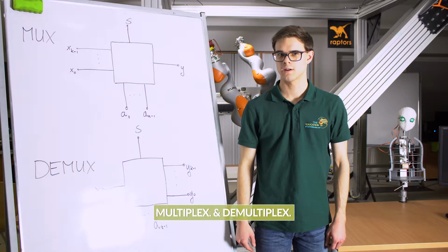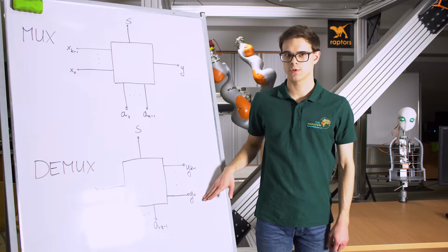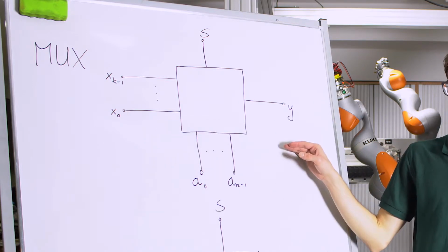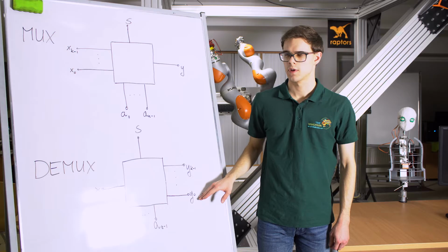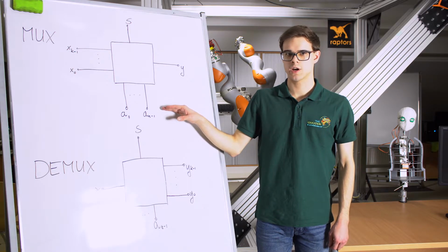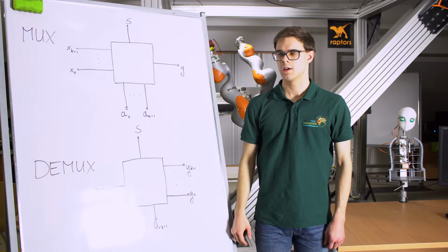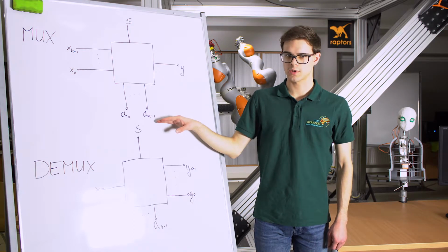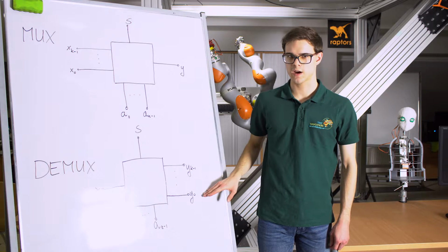There are also other, more advanced logic circuits, which are multiplexers and demultiplexers. Multiplexers have many inputs and one output, while demultiplexers have only one input and many outputs. Both have address lines which are required to differentiate data input. You can send a batch of data on one line and the multiplexer will select the input, giving data a corresponding address, while the demultiplexer will transmit this data to a specific output.